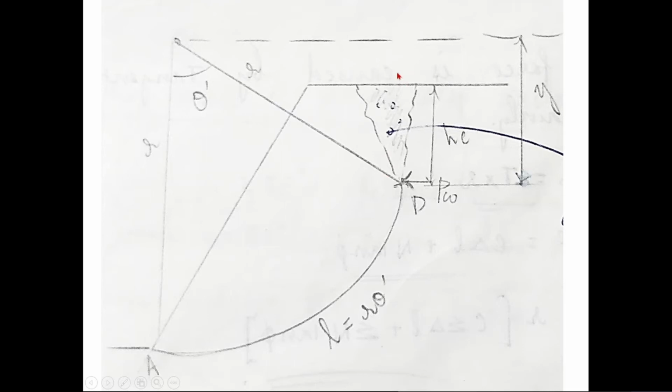Suppose when it rains, this gets filled with water. This is my new condition here. Now, the depth of my tension crack is Hc. And when this tension crack comes, what happens? Along this much length, my cohesion is not going to mobilize, isn't it?